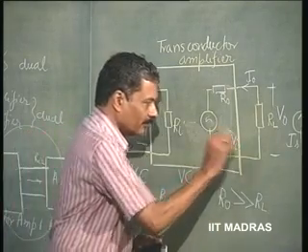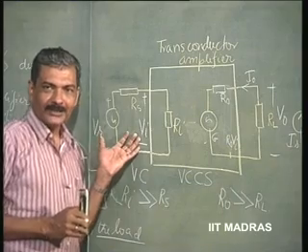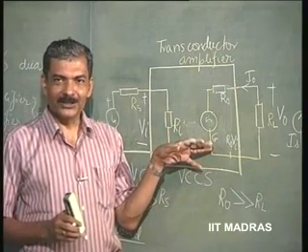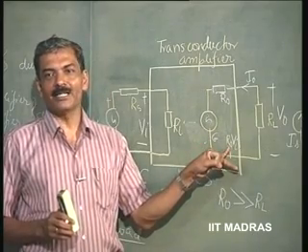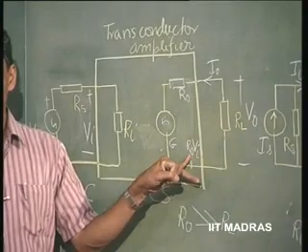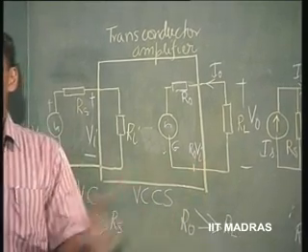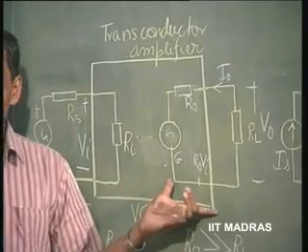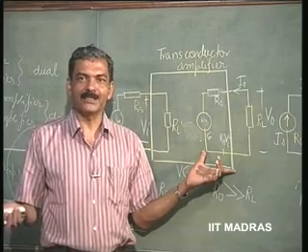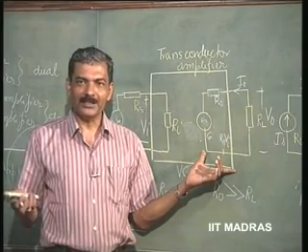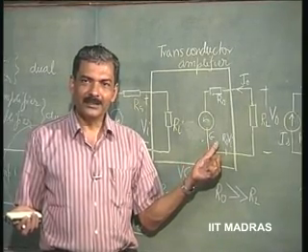So, now this was voltage controlled, this has now become a voltage source, and this G times R naught is what we have earlier defined as K. So, this is K times Vi. So, now we have already evaluated for such a voltage controlled voltage source the voltage gain and current gain. So, the same expression is valid for voltage gain and current gain, except that K has to be replaced by G times R naught.